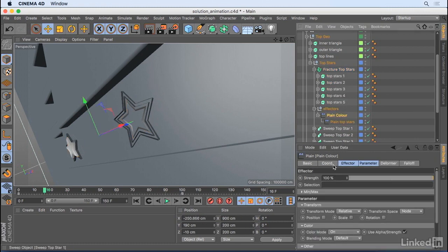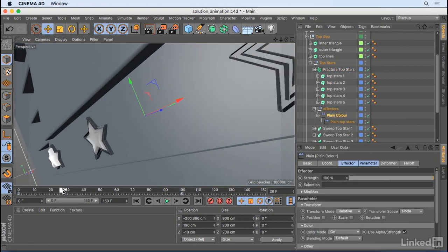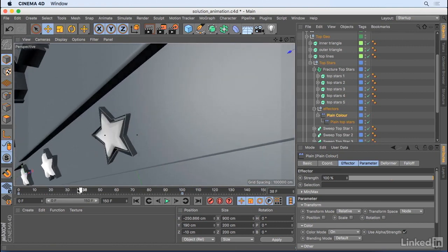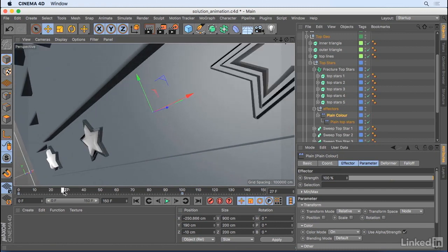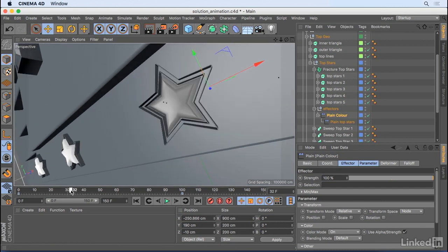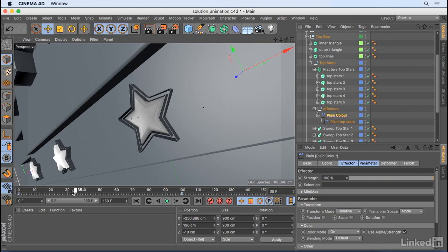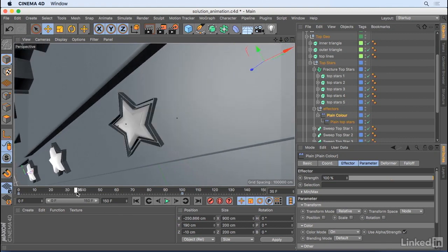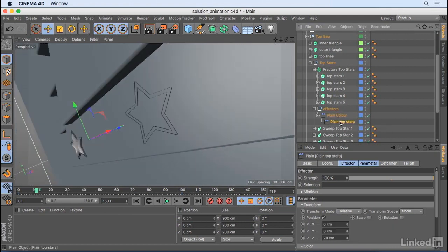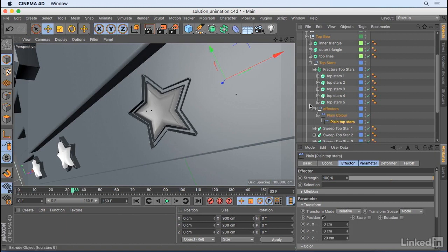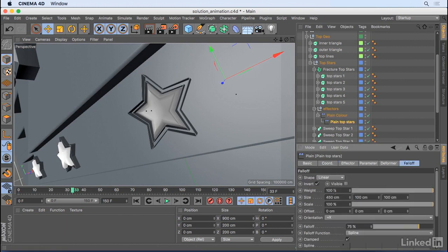That means you can then control the, if I scrub through, you can see they're almost fading in. I knew when I wanted these to fade in so that when I come to texture them using a MoGraph shader, I can have their opacity change. So they're fading in and they're moving as well. This is what the second one is doing. If I enable the fall off, it'll be very easy to see. So if I just make those visible.